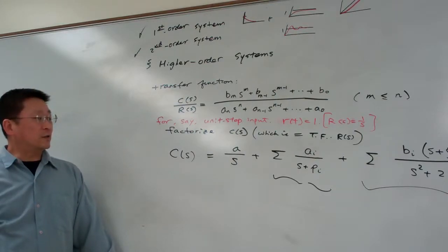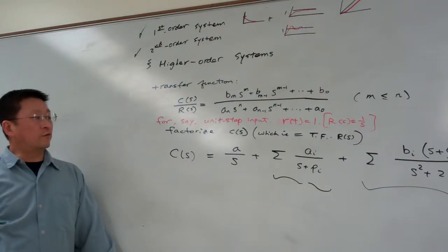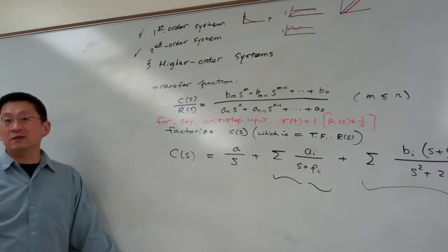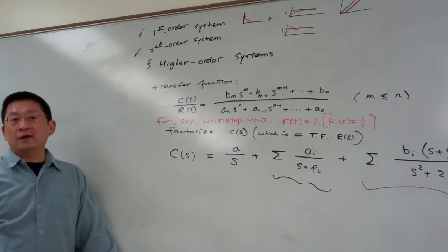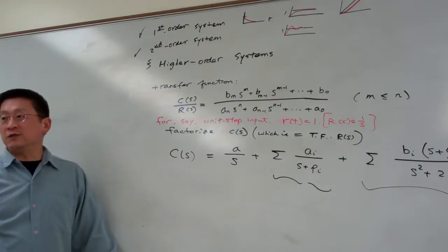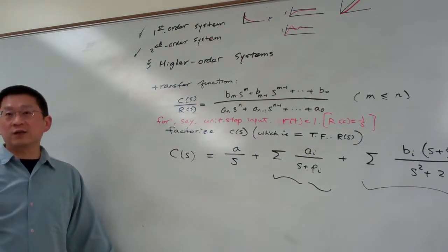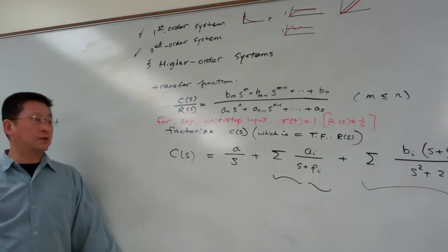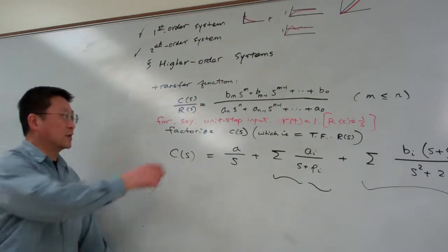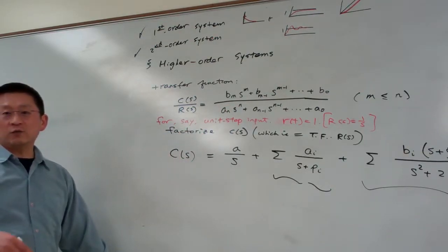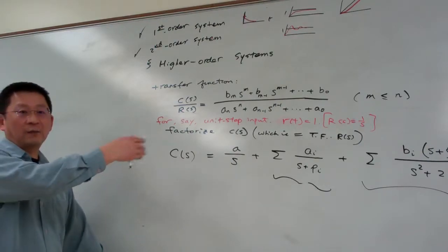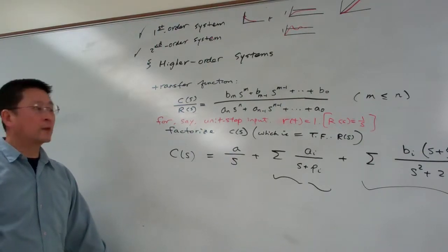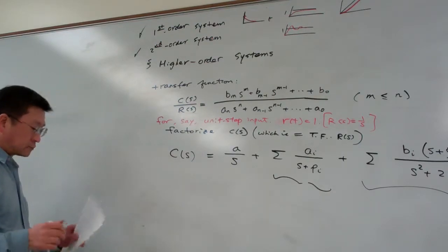Usually software like MATLAB will help us factorize. But most of the time for control systems, if the degree is higher than 3 or 4, we can use engineering intuition to approximate beforehand. So you don't need to be scared, and usually the degree won't be so high, because we should have some way before this step to simplify the system. But here we talk about the theory.